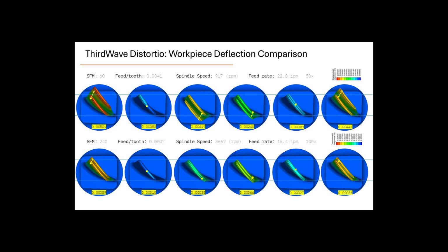It does increase the temperature at the tool-part interface, but it's still below the temperature we get out of the production module when we do the analysis. I don't show the graphs of the temperature data, but we're still below the recommended cutting temperature for the tool.